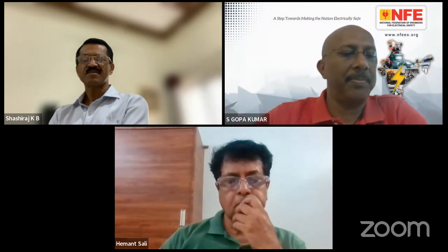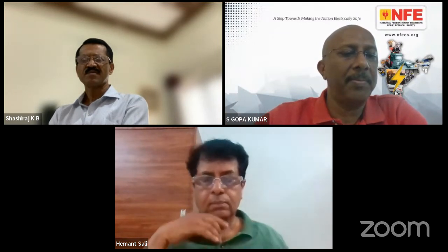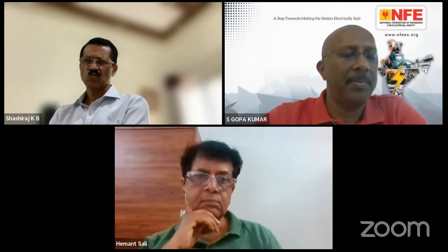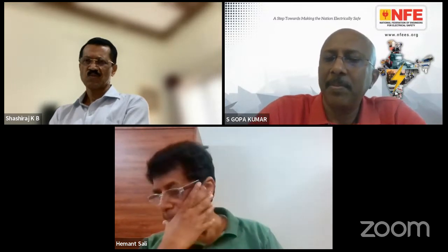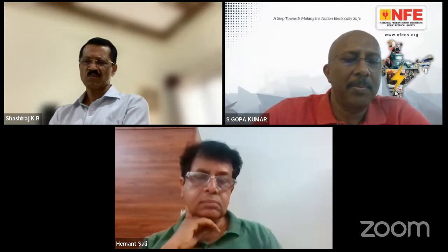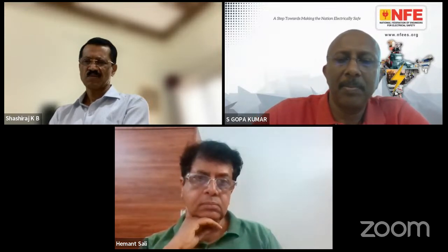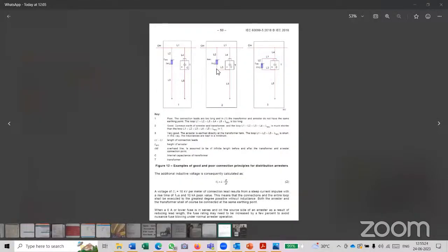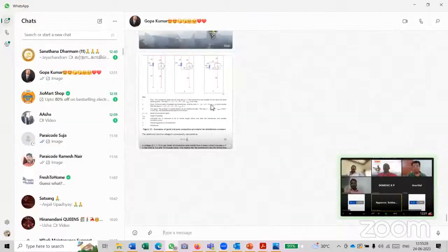Sir Joydhar, I have another question. For these lightning arresters, suppose in a structure we have 6 lightning arresters. These are going to 6 lightning earth pits, and all these earth pits are connected together through an earth grid. Now there is a separate earthing grid also for the electrical earthing. Can the electrical earthing and this lightning earthing grid be connected together on the same earth grid? That means I connect my lightning earth pit as well as the electrical earth pit, or I have to prepare 2 separate earth grids and then bond them together.